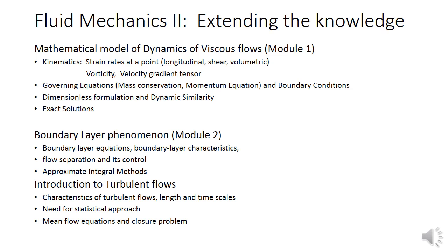Then the natural question arises that the conditions in the laboratory should be such that the actual real flow and the flow in the lab around the small model of the car should be in some way connected and dynamically similar. Otherwise, the whole exercise would be meaningless. So such routine testing in the labs is supported by dynamic similarity conditions, and the knowledge that comes from dimensionless formulations.